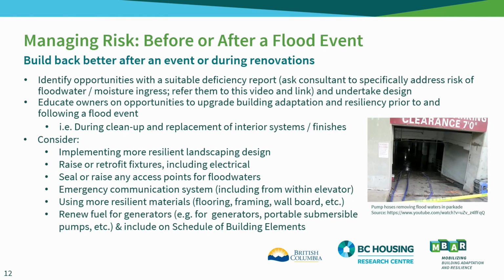Consider building back better after an event or during renovations to accommodate flood-resilient design strategies. Opportunities for this could be identified within a Strata Council's deficiency report. You can educate owners regarding improving building adaptation and resiliency prior to and following a flood event. Some of these resiliency improvements could include a more resilient landscaping design, raising electrical outlets, and sealing access points where floodwaters may enter the building.